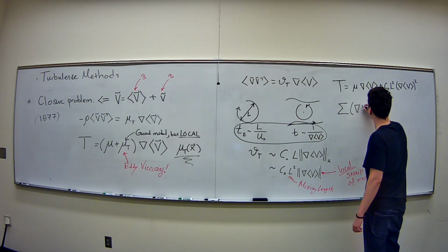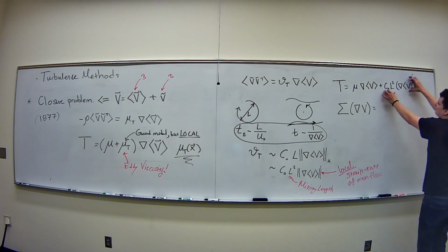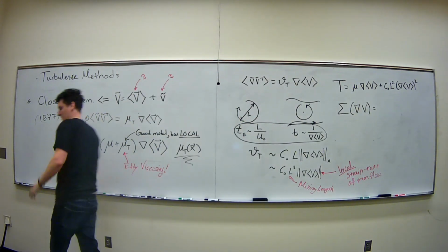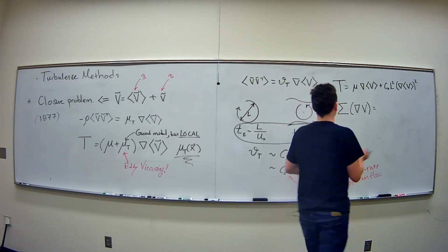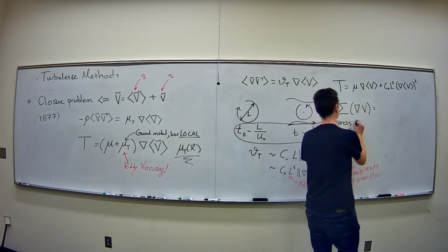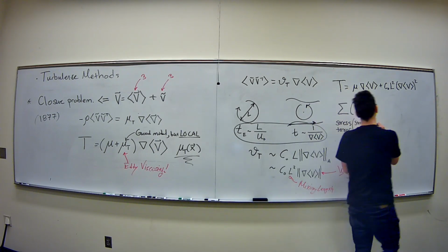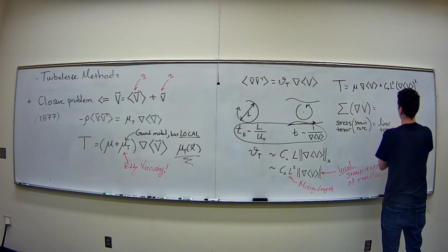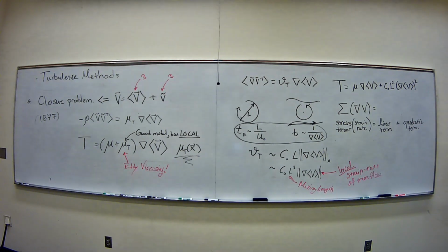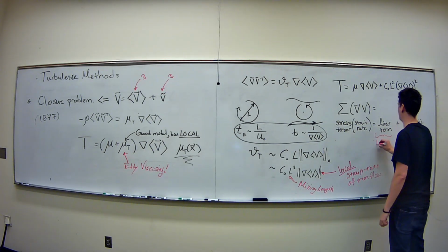I'm sick of drawing the brackets, but this holds even without the mean, actually, right? So this is the second order term, coming from this mixing length scale model. You see that happening where you have the stress tensor, which is a function of the strain rate tensor, equal to a linear term plus a quadratic term. So my inputs here, I have this linear term, which is the Newton approximation, right? So I really think of this as sort of Newtonian.